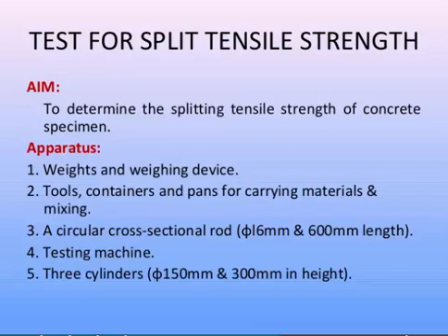A bearing strip of 3.2 mm thick and 25 mm wide is used, and the bearing strip is placed between the specimen and both the upper and the lower bearing blocks of the testing machine, or between the specimen and supplementary bars or plates if needed, and placed along with the sample.